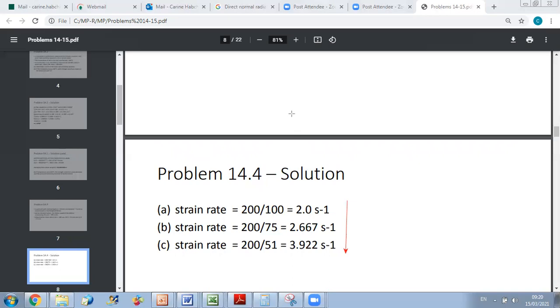Okay. Doctor, can you just tell me what the formula for the strain rate was? Yes. The formula for the strain rate is epsilon dot equals the velocity of the tool used for deformation over the height. For example, here you are compressing. You have this is your part, and this is your plate. Okay, it's V over H. So here the velocity direction is like this. Due to velocity, you are reducing height, so you will take into consideration it's V over the depth of your part, the height of your part.